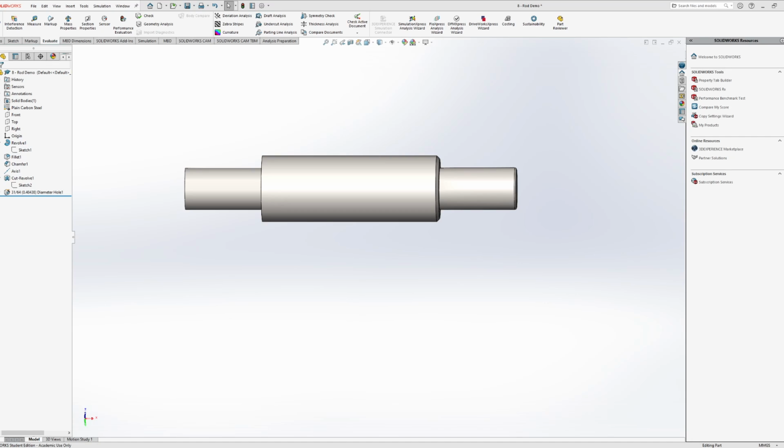So if you are doing even just a basic smart dimension, it should register that that is a diameter, even though from a two-dimensional standpoint it only looks like a rectangle. So I'm curious if the details of your geometry are correct. If that's the case, then we might want to look at some of the base sketches in relation to other details. Like, is the sketch actually in the correct place and orientation? Does that even have a length on the inside?